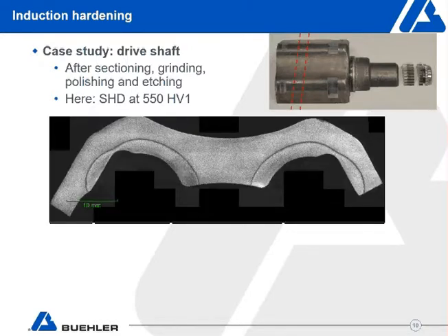And this illustrates an image where we've done a stitched up or mosaic of that component. And sometimes if you've got a system that can really scan your samples, it just gives you a lot more versatility on how many locations you can test to just validate that your component is okay. So this is a stitched-up image taken from the hardness testing. And you can clearly see, for an edge surface, the transition from the induction hardened bit, which is that region I'm highlighting there with the cursor. And then the red point highlighted there is the transition from the hardened surface onto the core material.